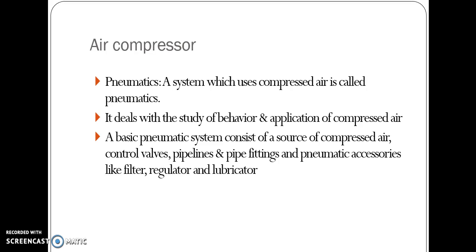By terminology, pneumatics is the study that deals with the behavior and application of compressed air. A basic pneumatic system consists of a source of compressed air, control valves, pipelines, and pipe fittings, and pneumatic accessories like filter, regulator, and lubricator.